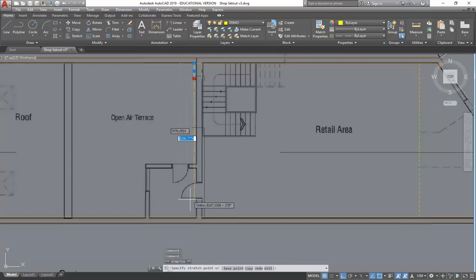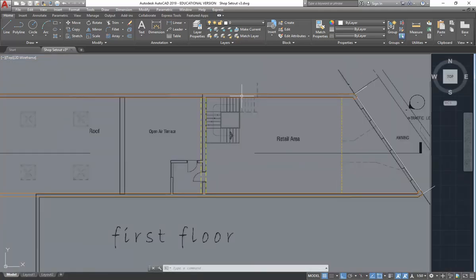But then the two that I'm left with, I can now just stretch down to touch the bottom. And then if you worked out how to change things to a different layer, so this is the last thing I'll do, and then I'll give you some time to try this. So I want to change these lines to the same layer my walls are on. So I'm just going to click onto them, so they're highlighted, and then up here, choose my walls layer. That easy.